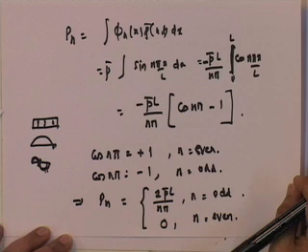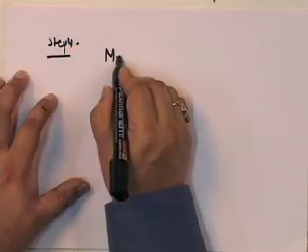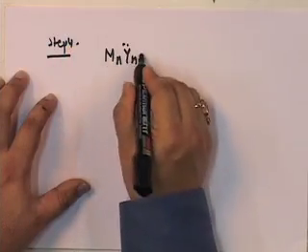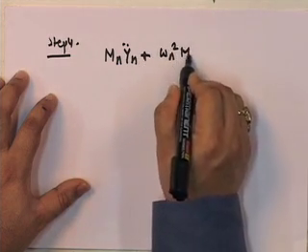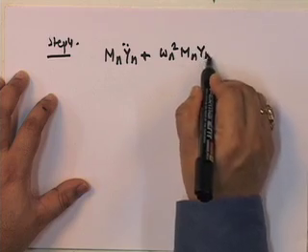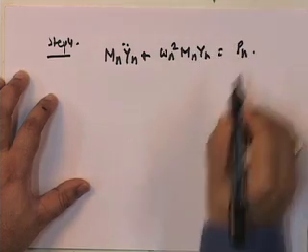And so, therefore, now what we have is step 4, which is to solve m bar y n double dot plus omega n squared m n y n is equal to P n.